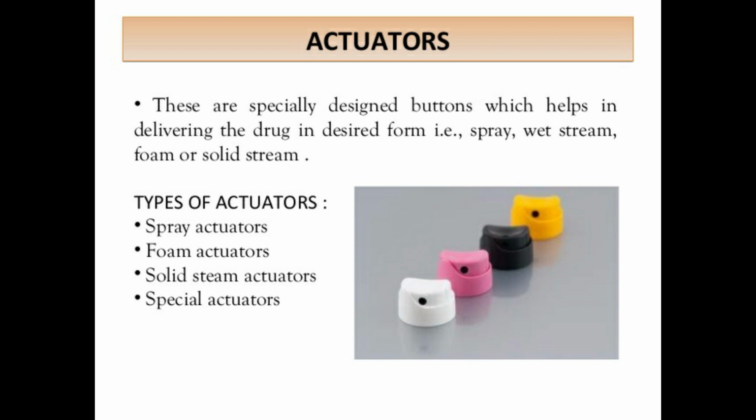So how does the actuator work? The actuator controls the fineness of the product spray as well as the amount of the product that is dispensed. When you press down on it, the valve is open. When the valve is open, the pressure is released from the top of the aerosol can and the pressurized propellant tries to escape from the can. However, the product filled bag prevents the propellant from escaping. So instead, the propellant pushes on the bag and forces the product out of the actuator.